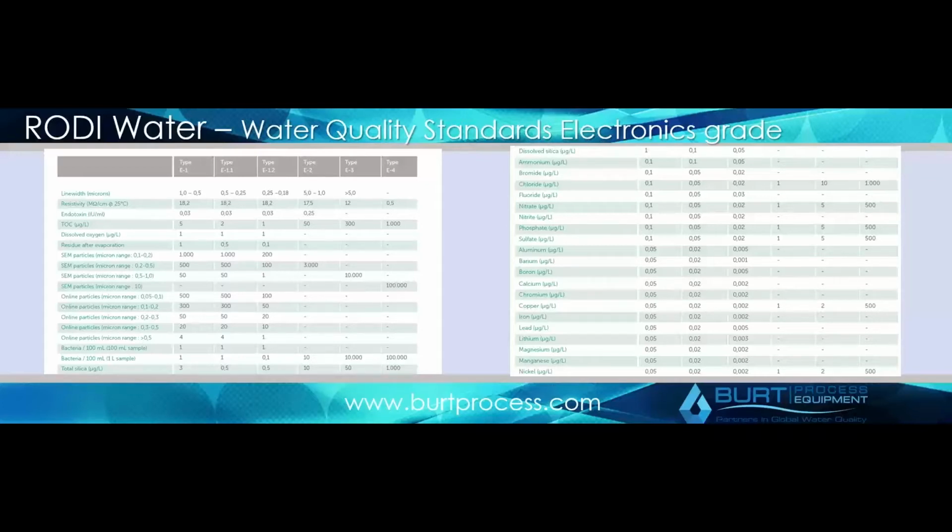And this is when you start getting into obviously much more intricately designed high purity, or what they refer to as ultra pure water systems. We're going to touch on this a little bit as we go along here as well. It does follow a lot of the same basic componentry, but as you can see, you can get into some very detailed and very specific kinds of water quality, which is why it's very important upfront in any project to have a good idea of what that water quality is, in addition to what your actual feed water quality is.